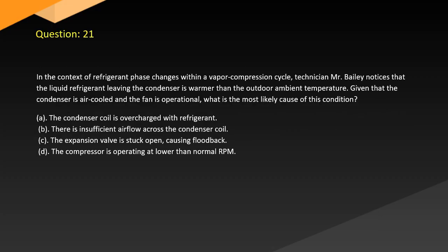Question 21. In the context of refrigerant phase changes within a vapor compression cycle, technician Mr. Bailey notices that the liquid refrigerant leaving the condenser is warmer than the outdoor ambient temperature. Given that the condenser is air-cooled and the fan is operational, what is the most likely cause of this condition?